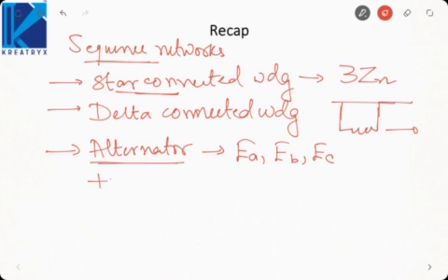Then we saw the positive sequence network and observed that since fault current is 0 power factor lagging, it will lie along the d-axis and it also rotates at the synchronous speed in the direction of rotation of the rotor. So the relative distance between the rotor or the field axis and the armature MMF does not change and it always lies along the d axis. So we kept x1 is equal to xd.